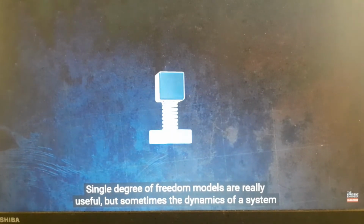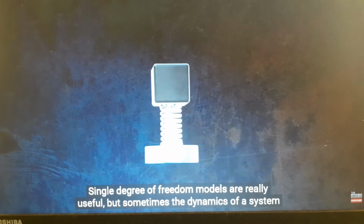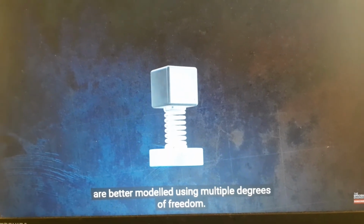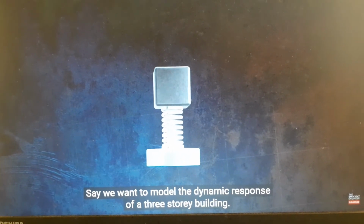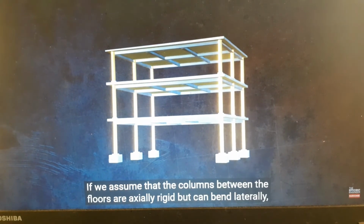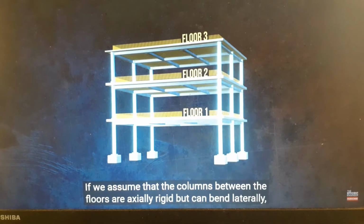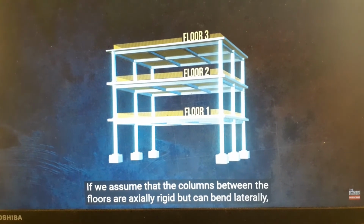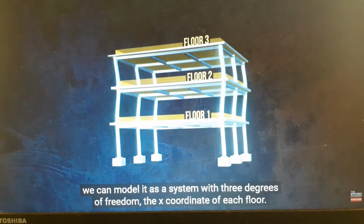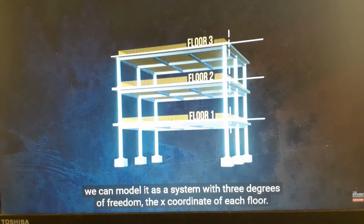Single degree of freedom models are really useful, but sometimes the dynamics of a system are better modeled using multiple degrees of freedom. Say we want to model the dynamic response of a three-story building. If we assume that the columns between the floors are axially rigid, but can bend laterally, we can model it as a system with 3 degrees of freedom, the x-coordinate of each floor.